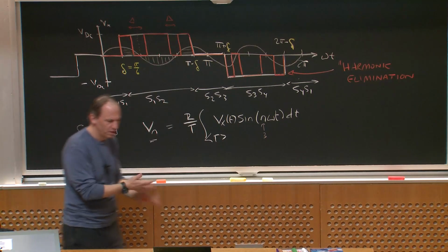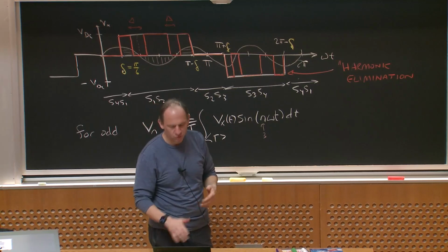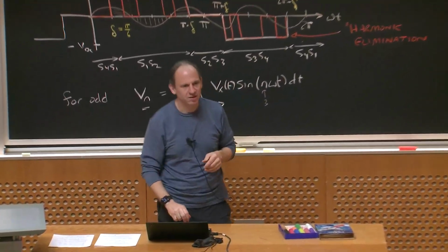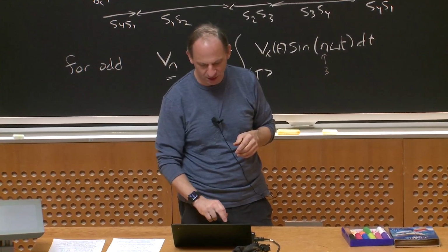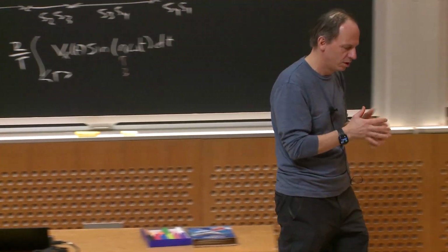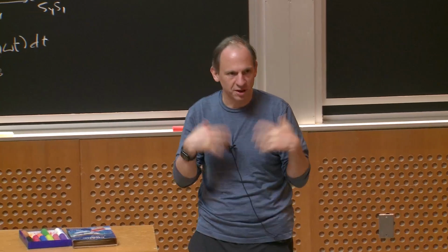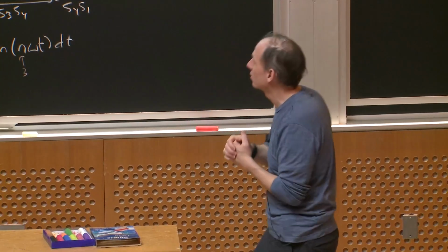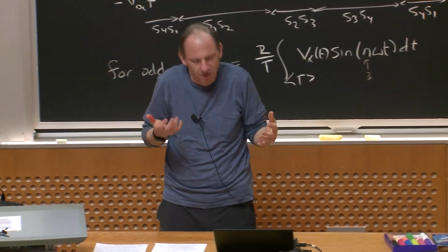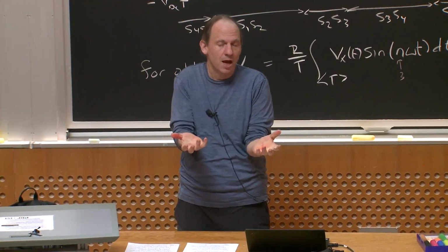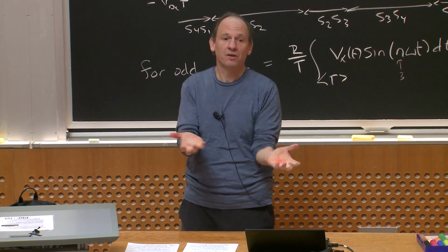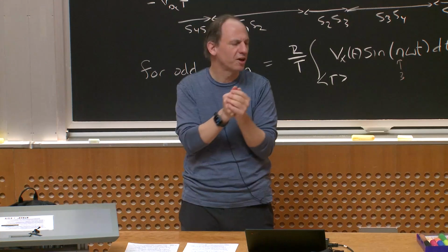No, it turns out that, and you can write equations and start solving them to do this, and I've given in KPVS chapter 8, there's 2 references. There's a classic Patel and Hoft reference that introduced this general idea, and then there's a more recent Chasen reference that really goes into detail about the best ways to do this. Each time you put in 1 pulse in a half cycle, you can ultimately pick 1 harmonic to eliminate. And when we talk about 1 harmonic, we're keeping everything half-wave symmetric, so we care about 1 odd harmonic. Okay, so we're assuming our evens are all gone.